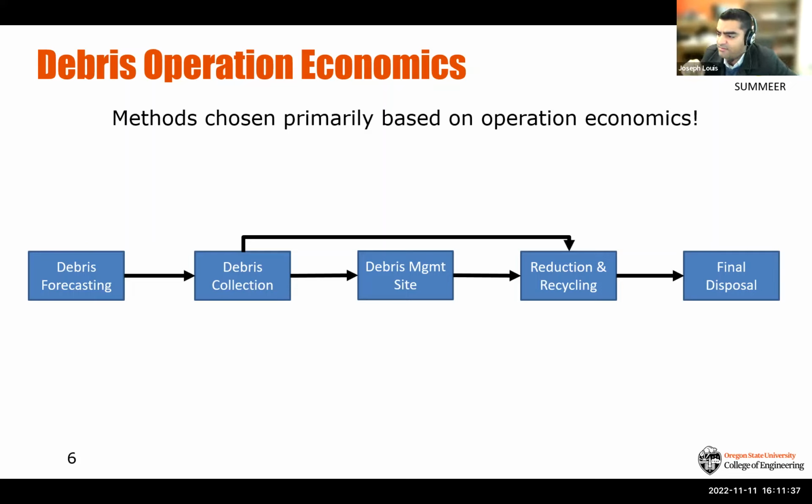And then you have debris collection, taking the debris to debris management sites for temporary processing, especially when you don't have landfills available in the near vicinity. And there you can reduce and recycle this debris before it's taken for final disposal, right?